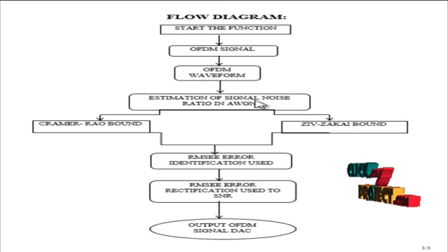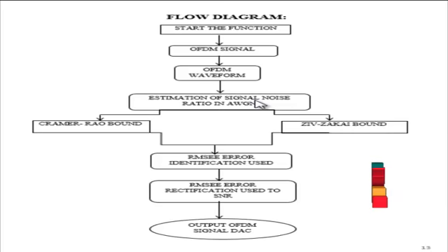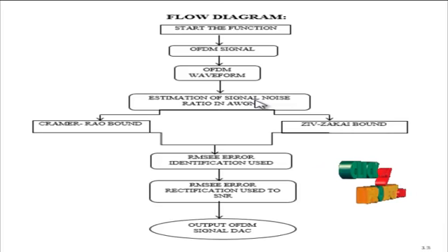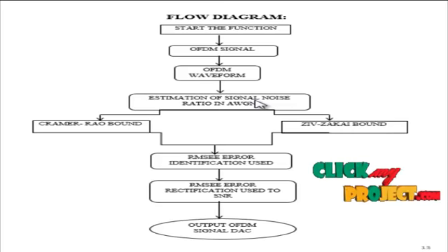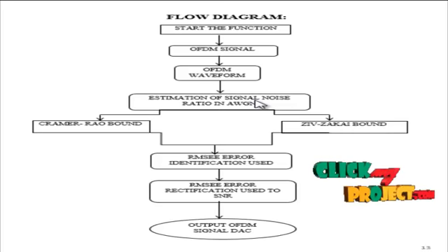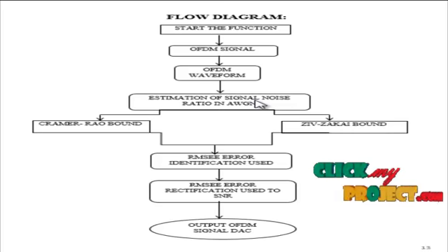Next, the digital to analog converter. The OFDM signal is converted by the DAC to a continuous time signal on the sampling interval. The impulse response of the DAC is denoted with windowing functions that limit in time the sinc interpolating functions. Thus, instead of using the widely adopted ideal model, this study adopts the realistic OFDM waveform, hence considering the actual output of the DAC using a Hamming window function, and the TOA RMSE performance of the realistically modeled OFDM signal.